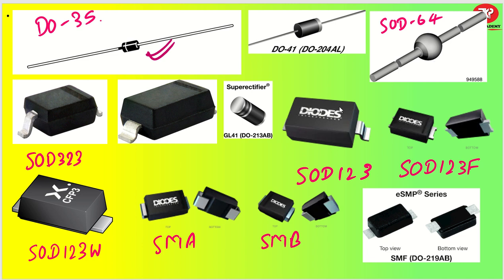Even SMD packages are coming up with power-like capacity, a little bit higher capacity, let's say 1000-volt breakdown or something like that. However, we have SOD323 package, okay, this is also almost the same package. We have DO213AB package, we have SOD123 package, and one more thing I'll tell you, in SOD123 package, okay, there are different kinds, whether it is SOD123 or SOD123F, 123W, 123D, a lot of different extensions that are given by different technology of the pads.